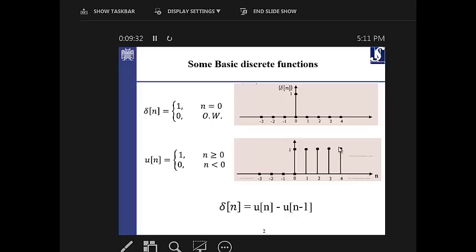When you take the samples, you're taking a sample every t seconds. So here is the first sample. Then after t seconds, this t should mean a fraction of a second, for example every 125 microseconds. If this is the period of sampling, then the frequency of sampling is 8 kilohertz. So if you take the samples every 125 microseconds, it means that you're using a sampling frequency of 8 kilohertz. So every t seconds, which is this amount, you take one sample, and so on. So here it depends on t.